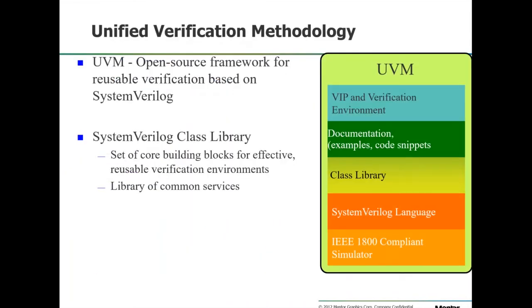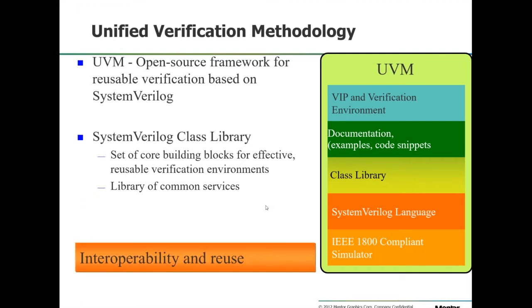So really, what is UVM? It's mainly a class library. So it's a set of base classes that you can construct your test bench out of. It's a set of methodologies of, how do I construct my test bench? How does my test bench start up? How does it run through to completion? What is the messaging? How does it shut down? So all of that is included in the UVM, so you don't have to reinvent the wheel by just using the base SystemVerilog language. So it's all about interoperability and reuse.